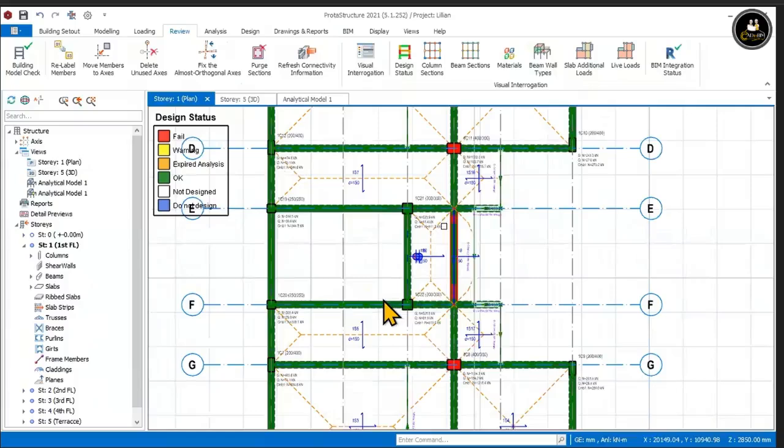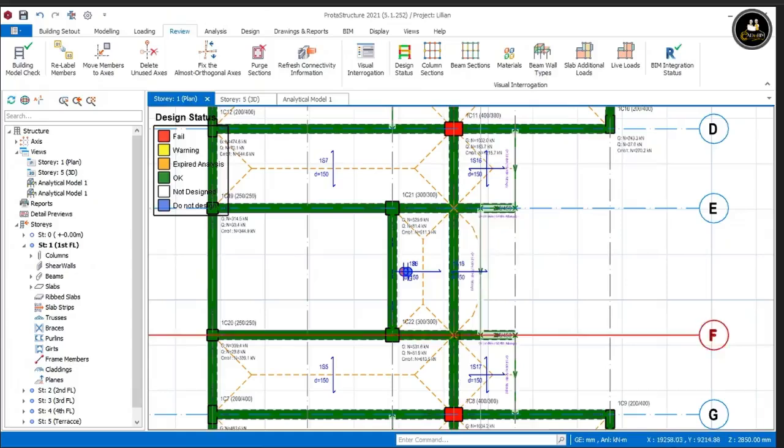On this drawing, I had two models. There is one in which I had put a column here at this intersection, and also at this one. But I saw this column and this one are so close, and it's only the stairs which is here. So that's why I decided to do another model without these columns, because I thought this area here is just the stairs, which need to be supported by these columns.